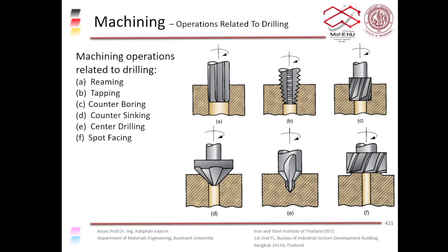Tapping is a process used when you want to produce an internal thread, to accept a bolt or a screw. So you use a tapping tool, which is called a tap.